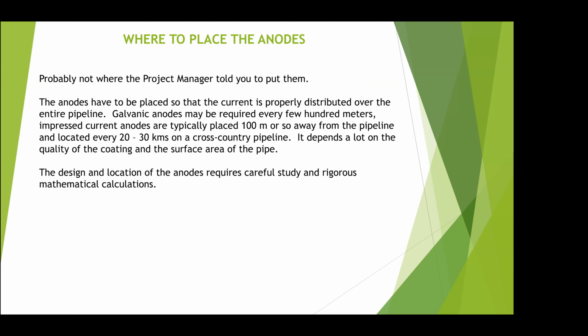With galvanic anodes, however, it's a different kettle of fish, because they don't have a big driving voltage. And depending on the soil conditions and the pipe conditions, you might need quite a lot of them. And that's rather analogous to, say, being in a big cathedral with no lights but candles.